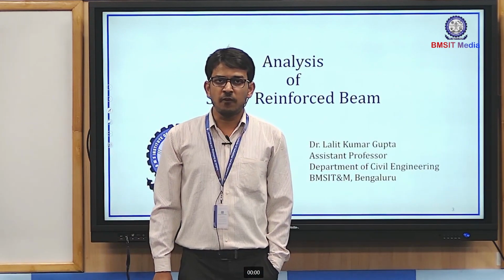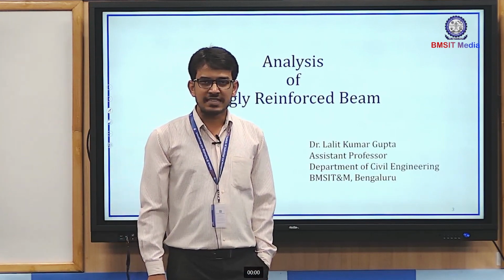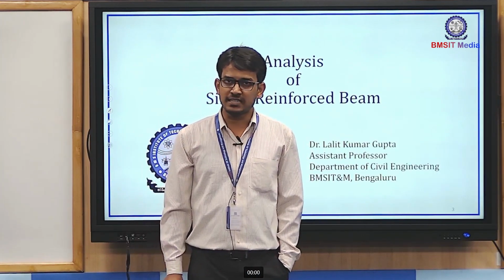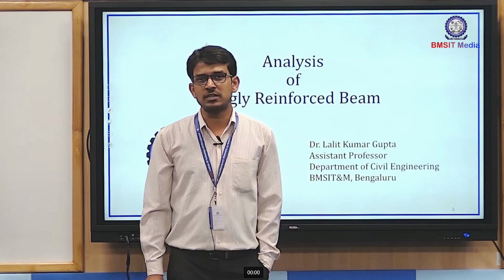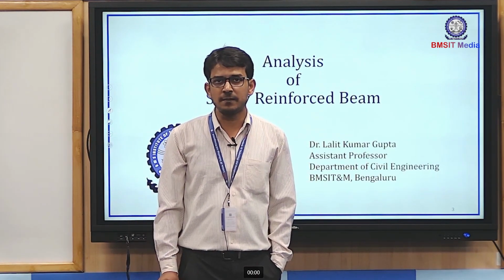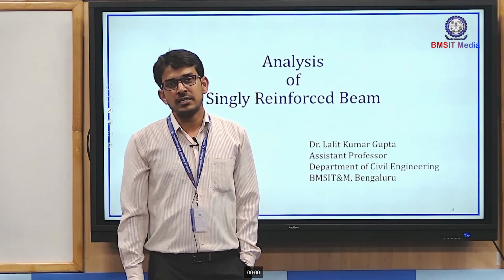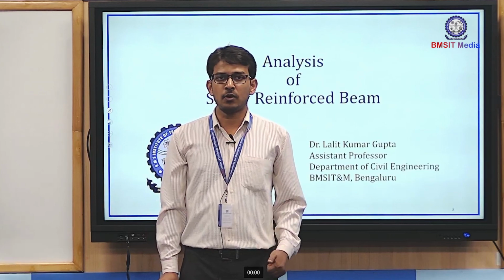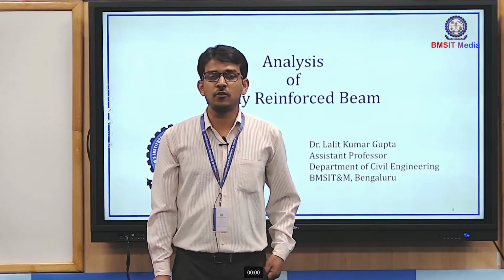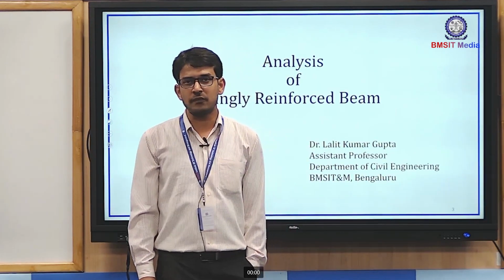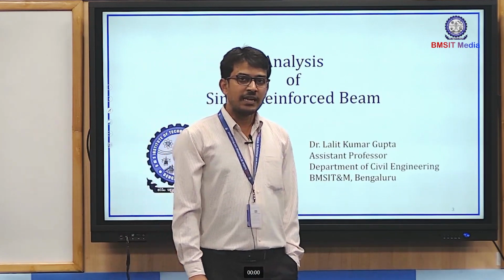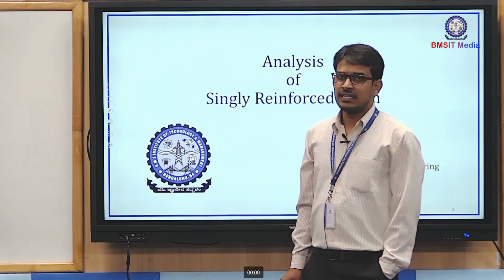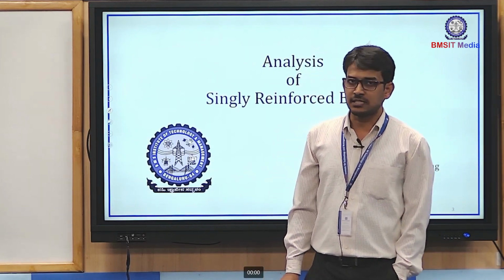In an analysis problem, the section of the beam is given to us, and the reinforcement we have provided is also given. We only have to find out whether the load coming on the beam can be taken by the beam or not, and how much moment of resistance is generated in the beam. If the section and reinforcement are given and we only have to calculate the moment of resistance, then such a problem is called analysis of the beam.